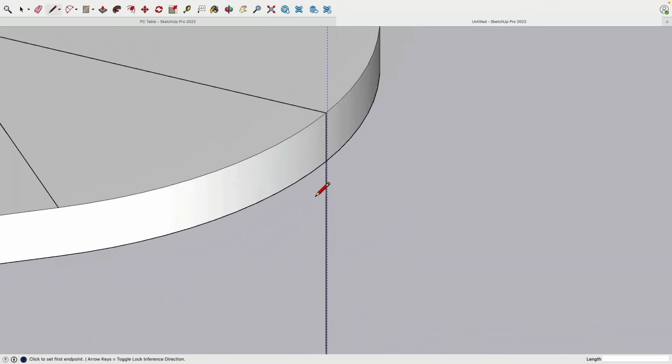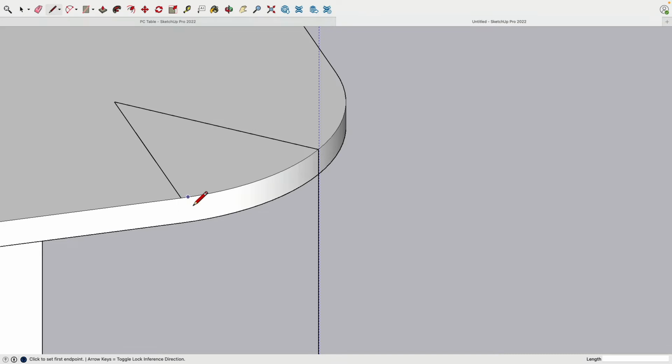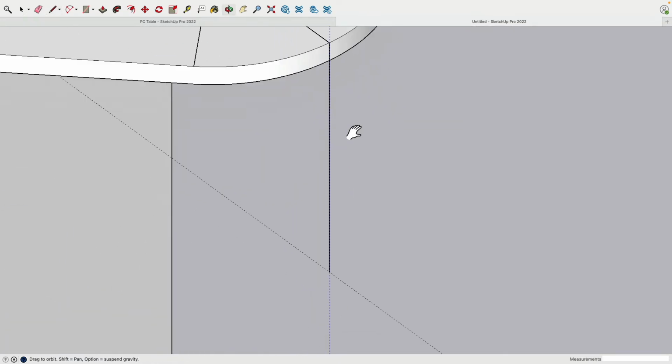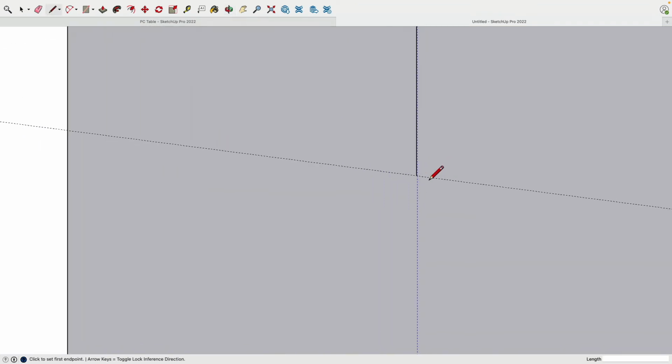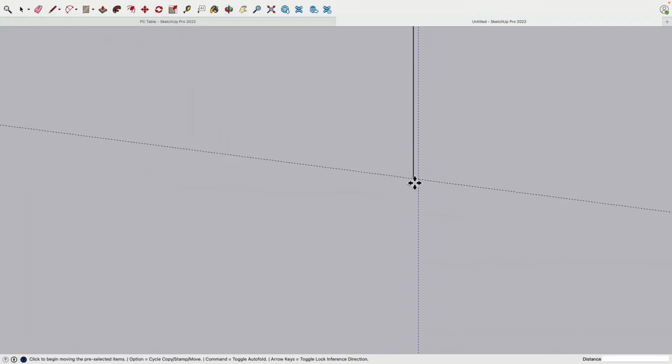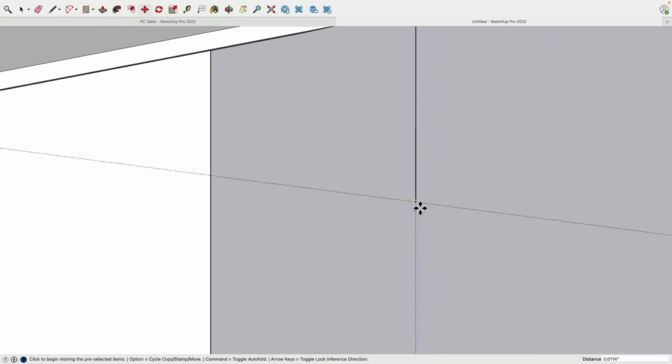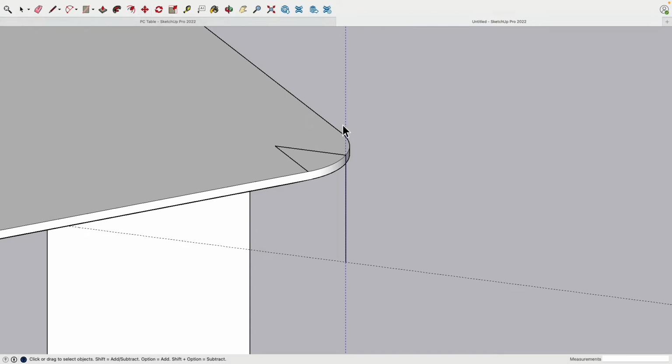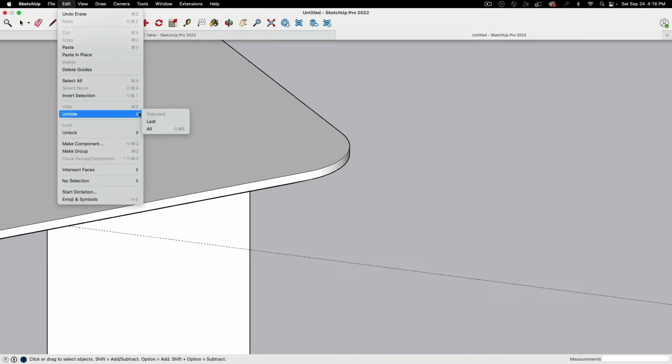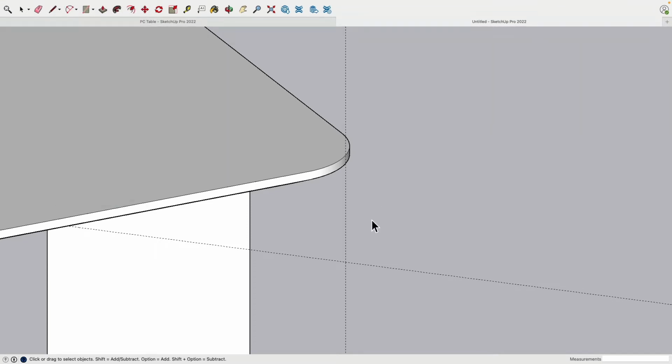There you see how I use basically the start of the arc and the midpoint and then 45° to draft this one out to find this. Now, if you want to be really super precise, and then this we just attach to this line. Very good. Now this guideline I would like to hide. So I right click and say hide it, and then this line and this line and this line I delete. These were just helpers. And then I go unhide and show this. Cool.